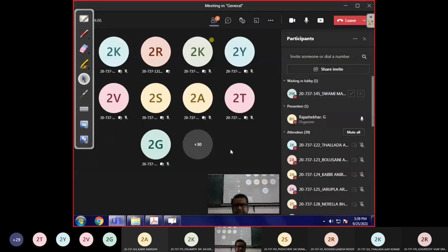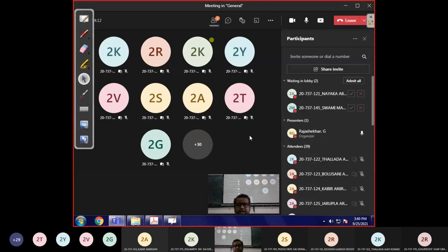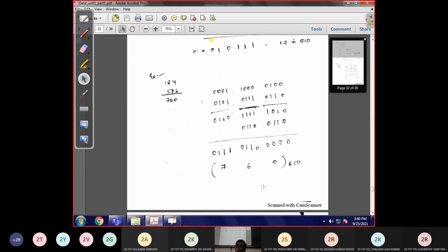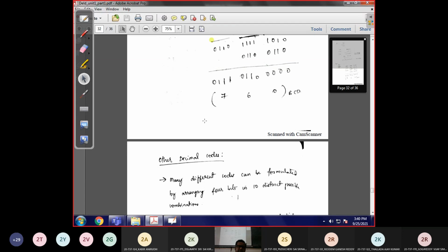Do you get the answer directly in BCD form? Answer my question, man. Do you guys get the answer directly in BCD form? No, right? Obviously, no. So just add 6 to that so that you get the answer in BCD form, like this here, 760. So this is the BCD code, and this is how you do BCD arithmetic.